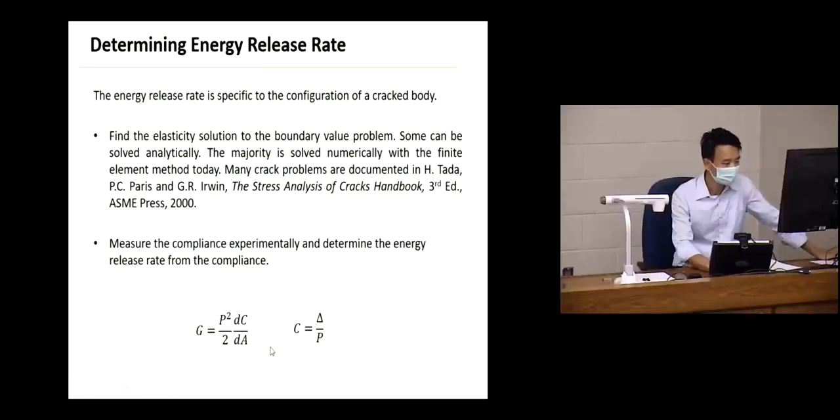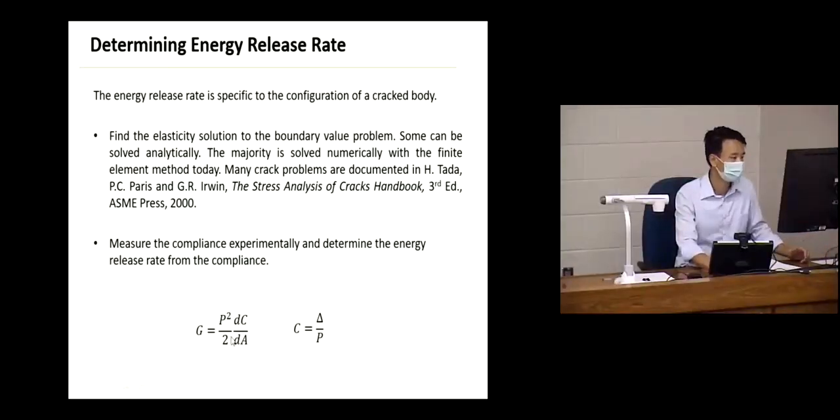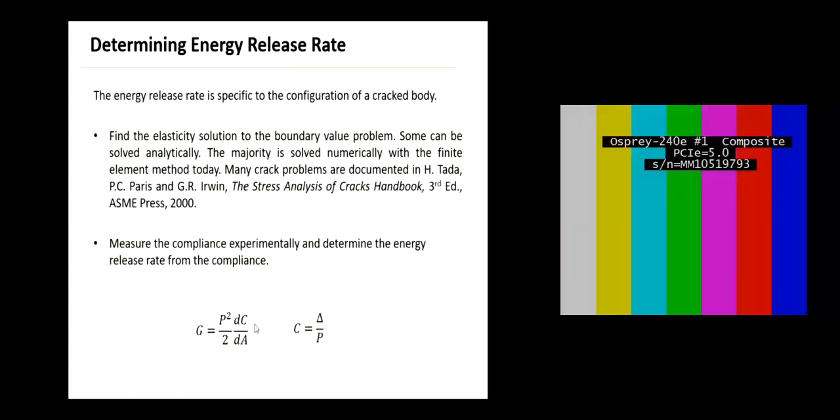So I show you, if you can calculate compliance analytically, that's great. Then you can use this formula and apply it. That's actually this first approach. You solve the elasticity solution, you calculate. But sometimes you don't, right? Because your geometry can be very complex. So back in the days, this is a very common technique. It's still occasionally used today. So you can do that by just measuring directly the compliance.